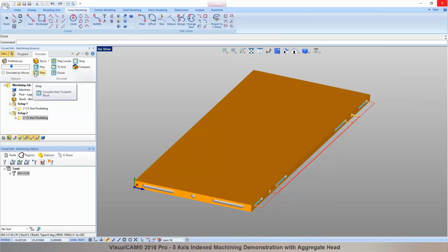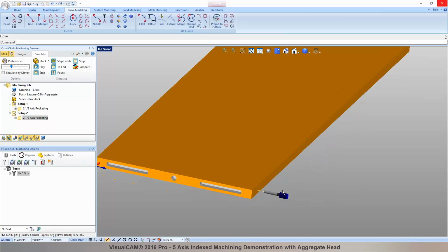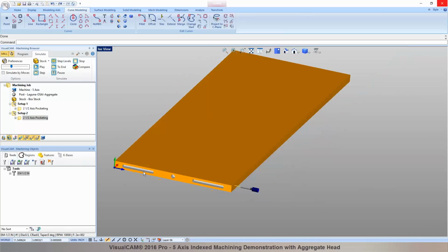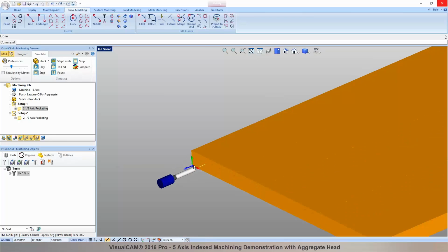So now, if you take a look at this toolpath in here, this is where the tip of the tool is, right? So you're going to be zeroing it out, this tip over here to this face right there. When you start the first operation, that's where you're going to be zeroing it out. That's your XYZ0 technically for cutting all of these parts, right? Okay. So if you know this offset in here, this distance offset.